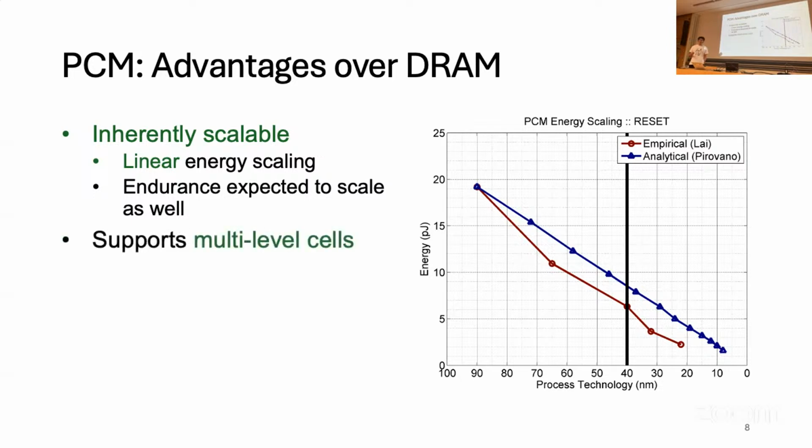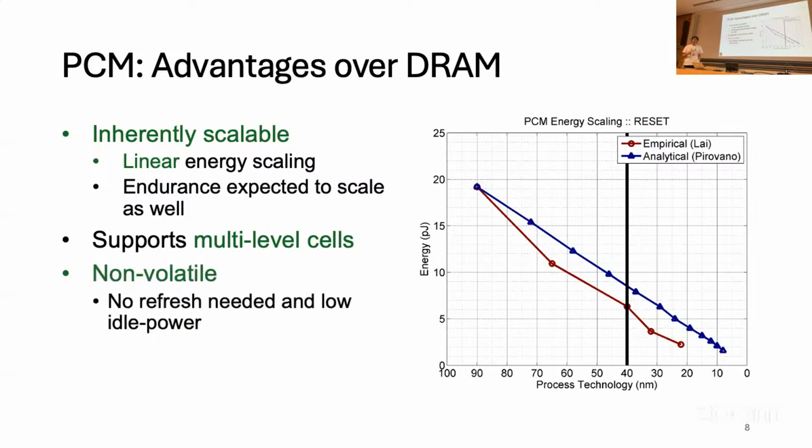The second advantage is that it supports multi-level cells. So we could potentially reach higher capacity as compared to DRAM. And it is a non-volatile technology, which means we don't need to perform any refresh to restore charge from time to time, as we have to do in DRAM, and thus it also consumes low idle power.